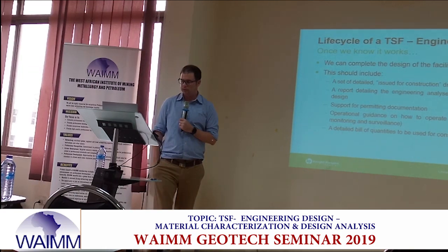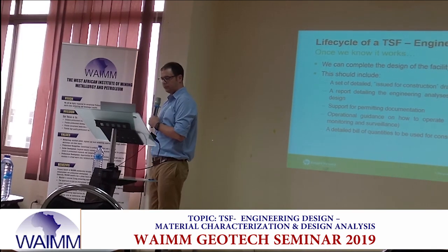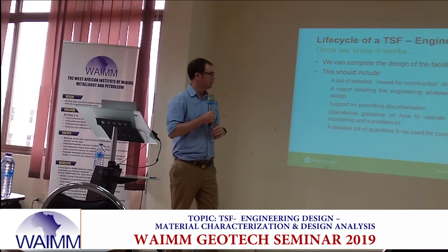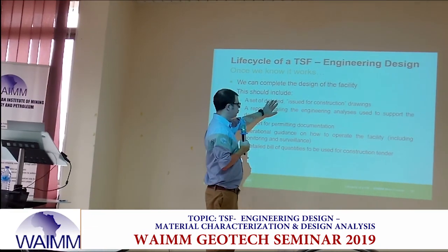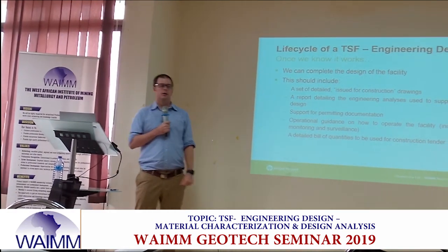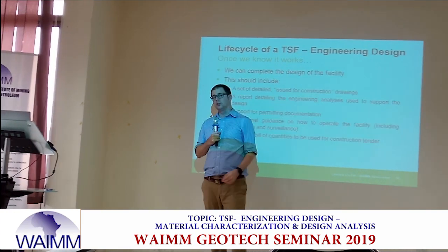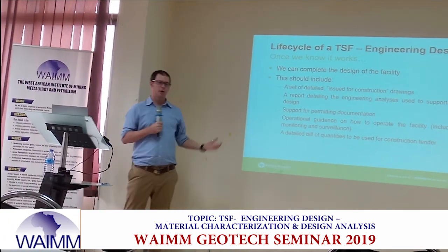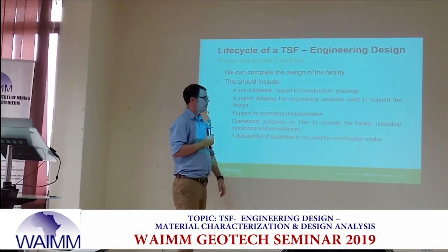Now, once we know it works, we can complete the design of the facility. It should include a detailed set of IFC drawings, issued for construction drawings, and a report detailing the engineering analyses used to support the design. This is huge. The engineering report. The drawings are all that we're worried about from a construction point of view. Okay? But a regulator, if you just come with a set of drawings, is going to say, well, these are absolutely beautiful drawings, but how do I know that it works? You've only told me what you want to do. You haven't shown me why we should be doing that. So that comes in with your detailed design report and your engineering analysis.